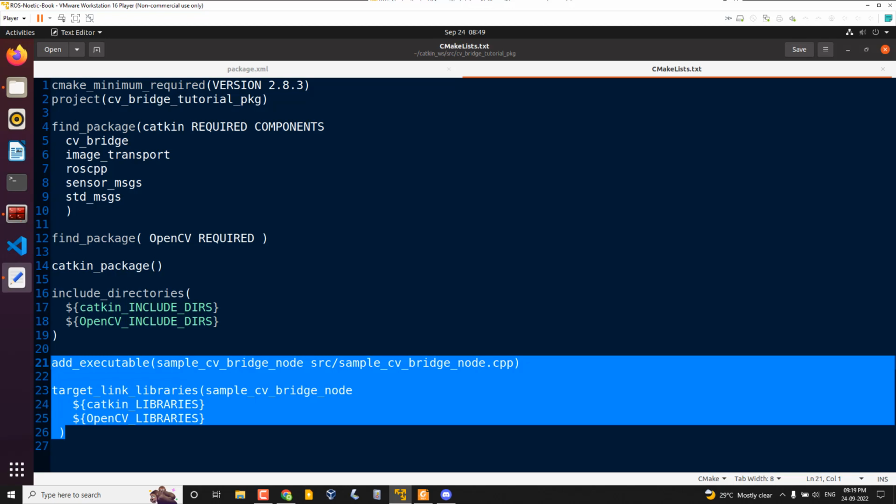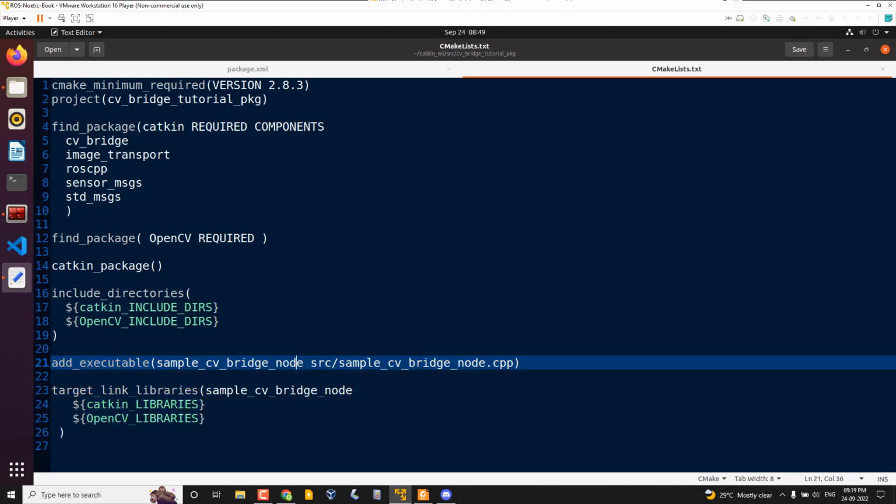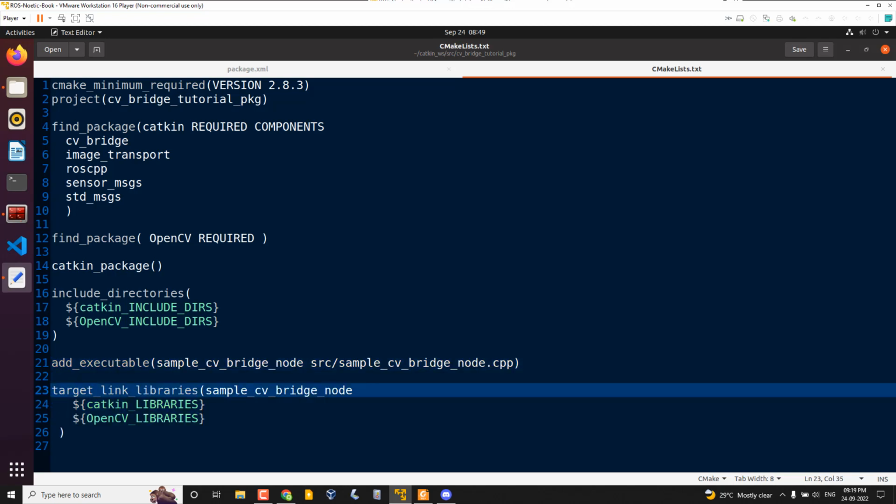If you are working with navigation, most companies are working on indoor robots and outdoor robots, mostly autonomous navigation. The navigation stack consumes only CPU. It's not GPU accelerated. So we have to optimize everything. That's what I want to say. C++ is a good choice even for ROS 2.